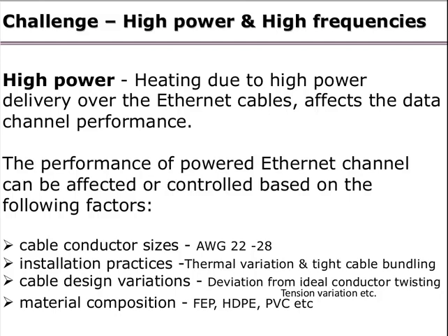For example, insertion loss due to dielectric loss is proportional to frequency. Since it is necessary for copper cabling to provide high-speed, low-latency access to the Internet while delivering high electrical power to the network devices, it is also paramount to deploy good quality cables that can serve these purposes.